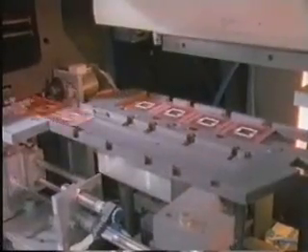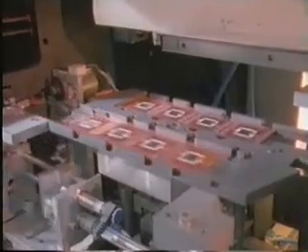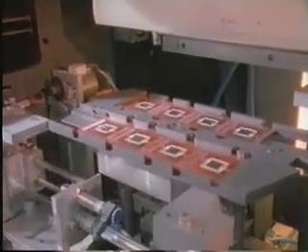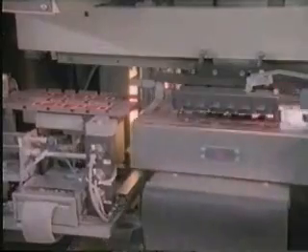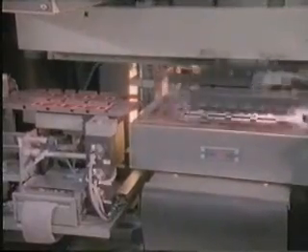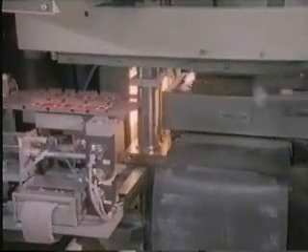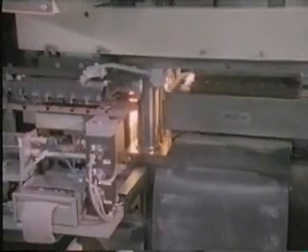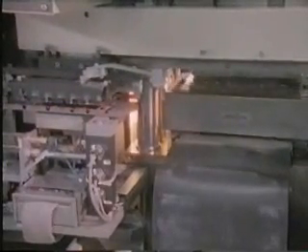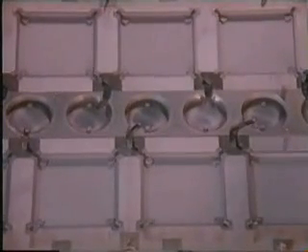To protect the circuitry and its fragile wire bond, the devices will now be encapsulated in hard plastic. This requires a 2-sided mold. Between each operation, the bottom mold is brushed clean. The circular cavities will hold pellets of plastic molding material. When heated, the melted plastic will flow through the small channels to fill the rectangular cavities which will hold the devices.